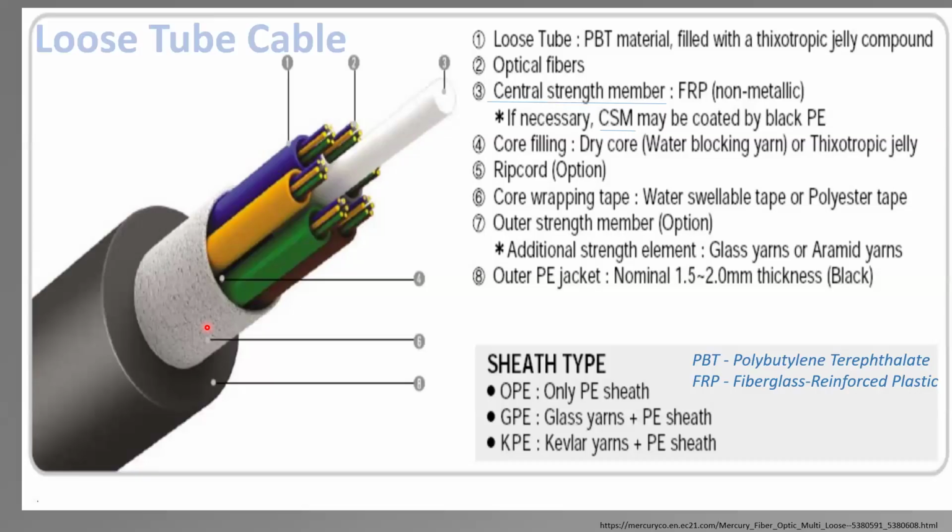In fact, I don't care how you're going to seal the tubes or pipes that are going underground, there's going to be moisture condensation that is going to eventually turn into water being present in those pipes that are underneath the ground. Which makes it a little bit more difficult for the wire pulling, but things are possible.